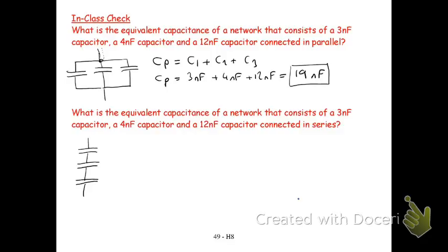Let's take the same scenario and now this is series, because imagine your point of interest. There's no junction, there's no choice. If current is flowing, all the current that goes through the first capacitor goes through the second, goes through the third. So if you think about it, current doesn't flow through a capacitor, it flows to a capacitor and causes the opposite electron flow on the opposite side. So it's a bit more complicated, but we can think of it as current flowing through for a while.